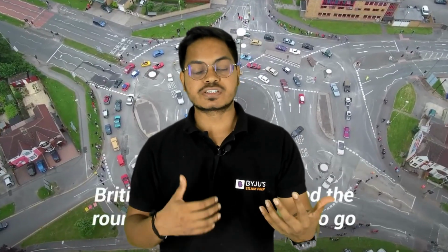The benefit of this traffic rotary system is that it works by itself. It is self-operational. We don't need any equipment, we don't need any police person to look over there, and it is going to work by itself. But if on any intersection we have a large number of vehicles which are going either straight or taking a right turn, in that case it is going to fail, and in this case we need to use the traffic signal.